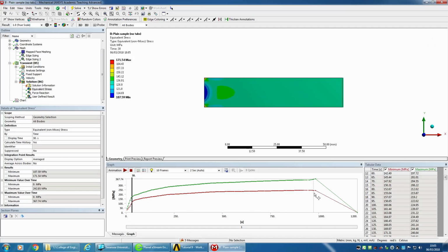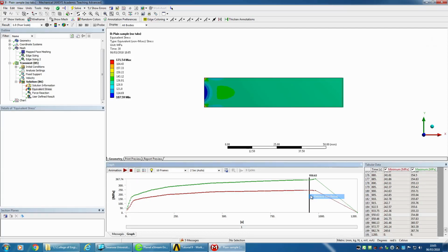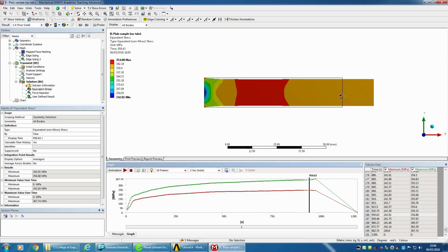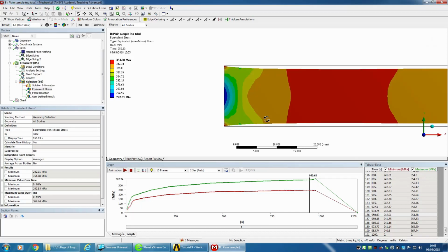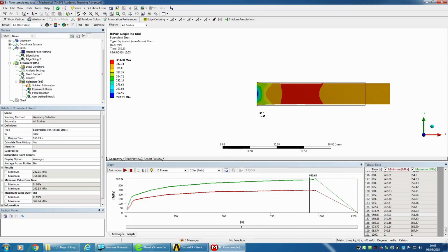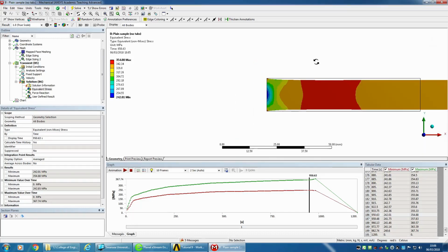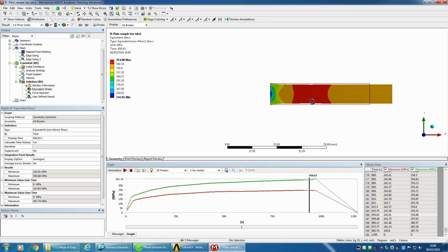And then we could say that somewhere along this point here, we've still managed to solve. We're getting this nice long deformation that you get when you're trying to capture the upper tensile strength. It's capturing that as well. But those boundary conditions on the left that we set are introducing a bit of a problem in the simulation. That is not particularly applicable. So yes, you do get the necking, but you're probably not going to get the breaking in the same location.